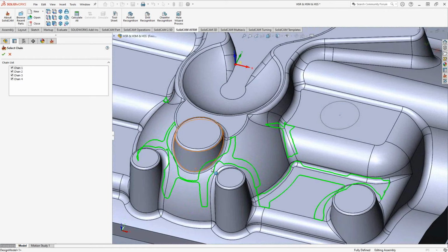That is in your rest milling option in the HSM technology section. Here, this is simply just the constraint boundaries, and this is a theoretical projection of where the tool might need to go in the case of the use of the reference tool.